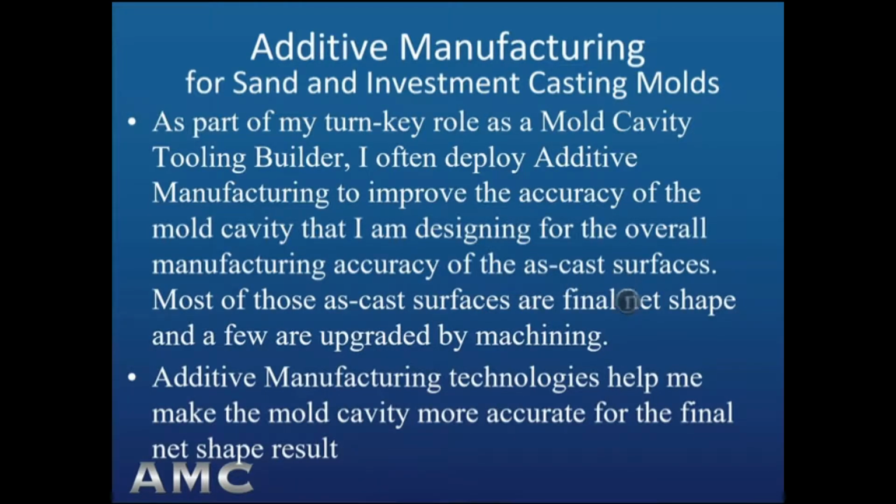Most of those as-cast surfaces are final net shape, and as we'll see in part 4 of this series, castings have high percentages of net shape that are as-cast, typically more than 80%, and lots and lots of times more than 90% are as-cast features net shape. So only a few are upgraded by machining, so it helps me to use additive manufacturing technologies to make the mold cavity more accurate for those final net shape as-cast results.